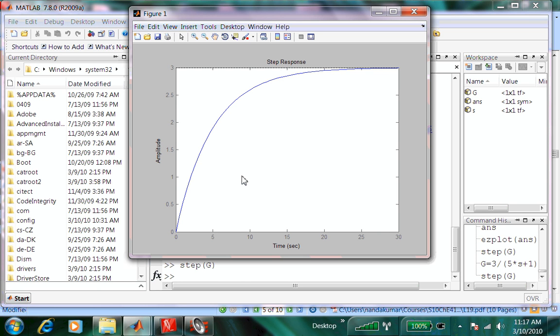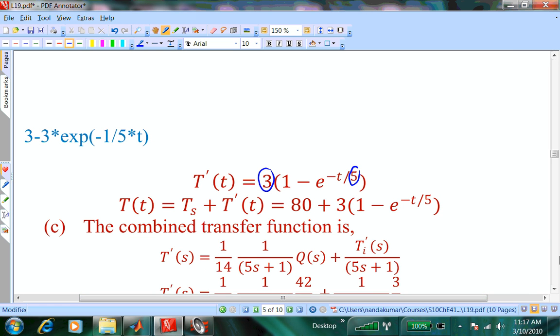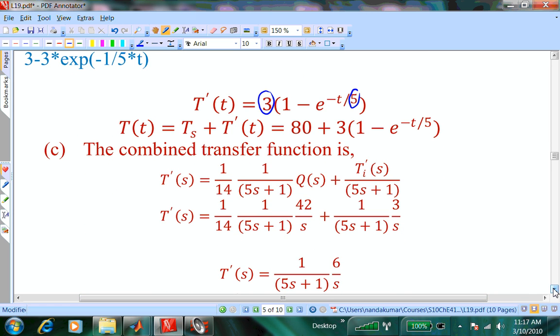Okay. Now in the next part, I'm going to do both of them simultaneously. That is, part C is I'm putting in 42 kilowatts and I'm increasing the temperature by 3. What do you think the output temperature will be? By how much will it increase? That's it. You get the point now, right? So it is additive. Superposition tells you that if you add 42 kilowatts, it increases by 3 degrees. But if you also increase the inlet temperature by 3 degrees, the net result is that the outlet temperature will increase by 6 degrees. Okay?